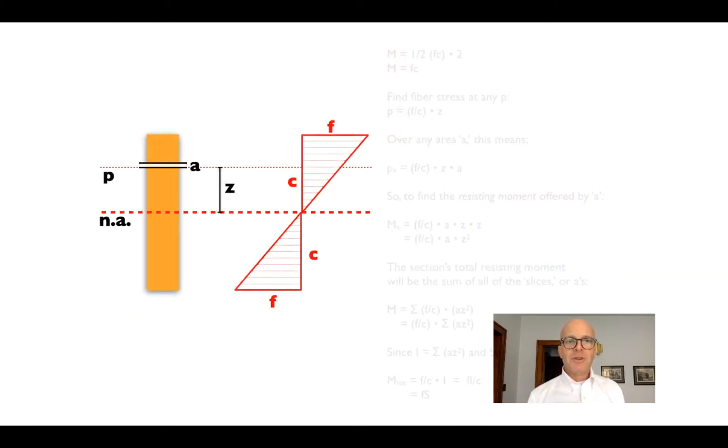So remember too, this diagram. I'm sure some of you are going to break out in hives to see all this again, but I'm showing this again just to show the other principle, if we look at the beam in cross-section instead of longitudinally. It reminds us that this line here, the neutral axis, at more or less the centroid of the beam shape, determines basically where the beam is going to have no tension, no compression. In other words, there's no reason to have any material there because it's not going to be able to resist the bending load that we're putting on the beam.